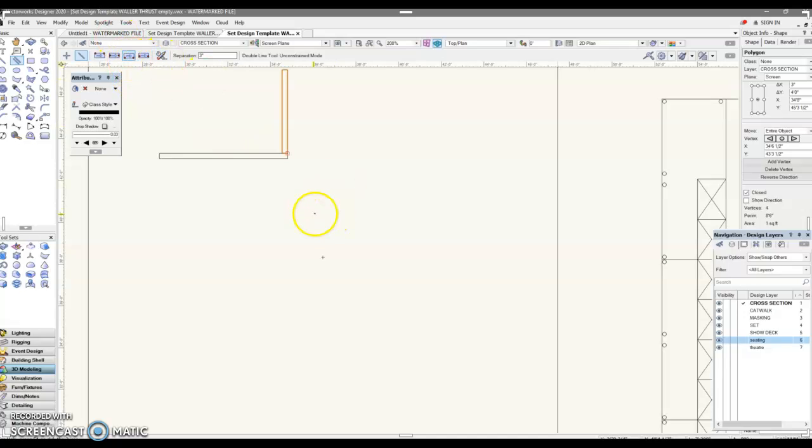And that's because I had the bottom line control line mode on. And so the bottom line, or the right side, if you're looking at the bottom from the right side of the paper, the bottom line of these two lines is what controlled where that went. If I'd have chosen the top line, the line would have been drawn so. And if I'd have selected the middle line, very useful, might have been drawn so. All right. So that's an important function of this navigation tool for the double line tool.